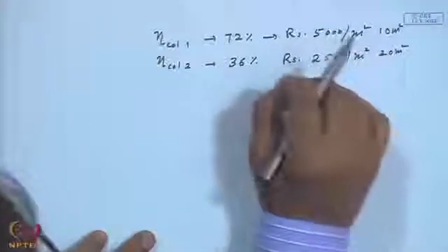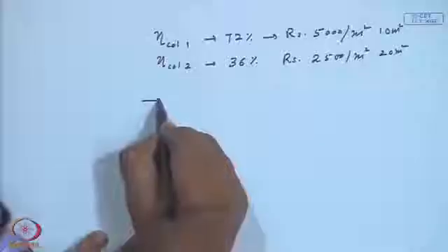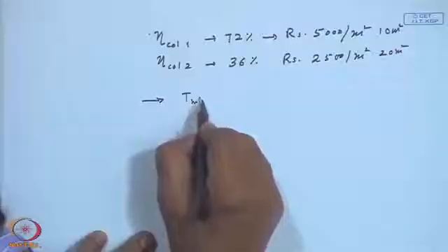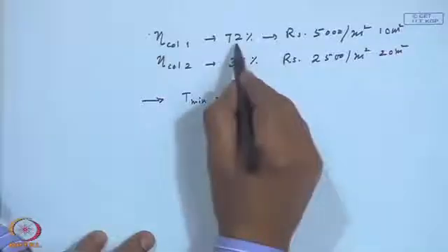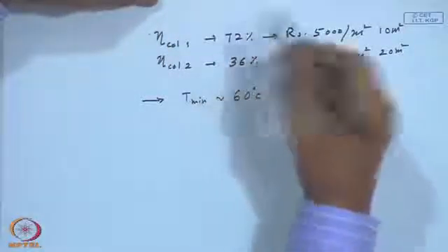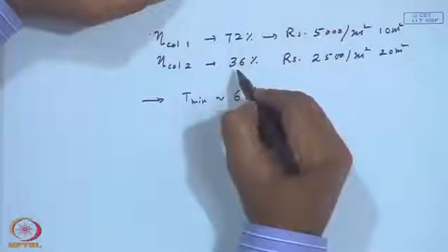So, apparently let us say my initial investment is the same, okay, for a given amount of energy apparently based upon the efficiency. But the issue is really, if it is required to deliver some T minimum, let us say 60 degrees centigrade, the collector with the higher efficiency not only delivers at higher efficiency, but operates over a higher period of time, whereas the collector with the lower efficiency will operate less period, because this will be having a higher critical radiation level than this one.